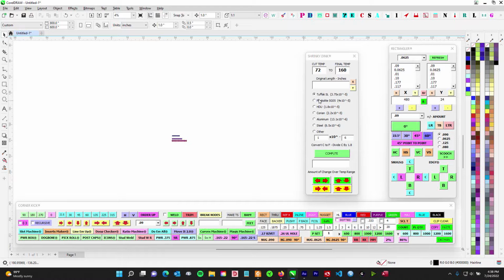So how do you find that information? I already have the usual suspects right here, but things like aluminum, steel, and concrete aren't really made by a company, so you can go onto websites and find engineering examples. That's where I found these. These are pretty constant, pretty standard. They are slightly different for alloys. Like this is a 6061, but it makes no difference. I think 13.0 was like 5052, whatever. Steel is the same thing. Your different chrome molies versus A36 are slightly different, but it's close enough.